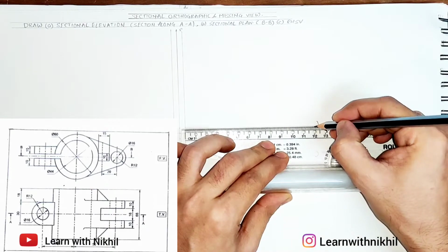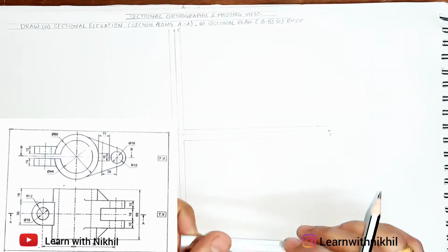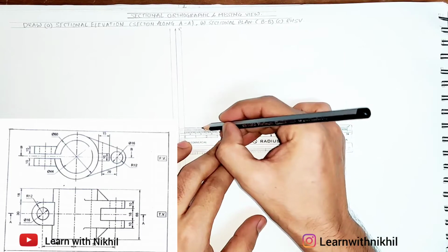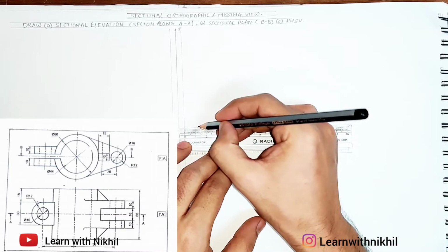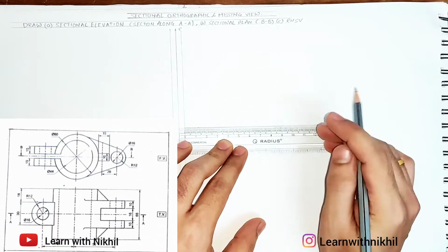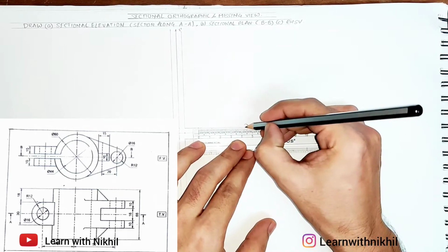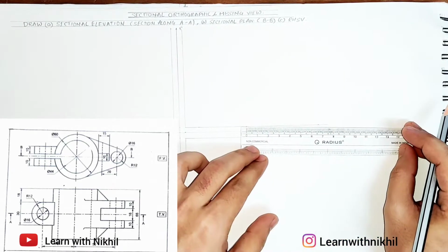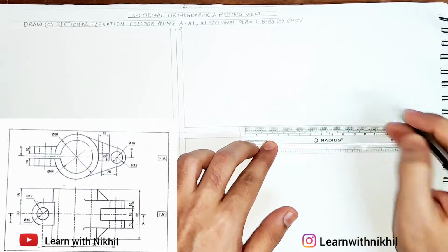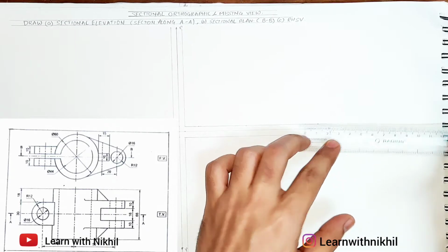As you know, the total width is 123 millimeters. We have already calculated that. So I'll mark a point 123 millimeters. Now I'll start marking the points. This is 12 millimeters. Then after that, we'll mark a point 44 millimeters apart from this point. This is 44 millimeters. Then from 44 millimeters, 55 millimeters. And after 55, the remaining part will be again 12 millimeters. So total distance comes to 123 millimeters.